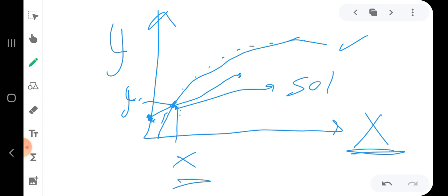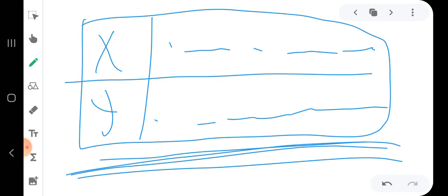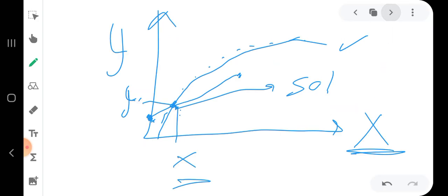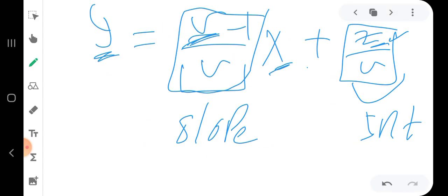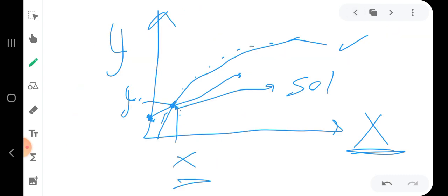So when I have the equilibrium data, I don't have a constant relative volatility. I need to use a graphical solution, and the solution simply will be the intersection between the material balance curve and the equilibrium relation curve.